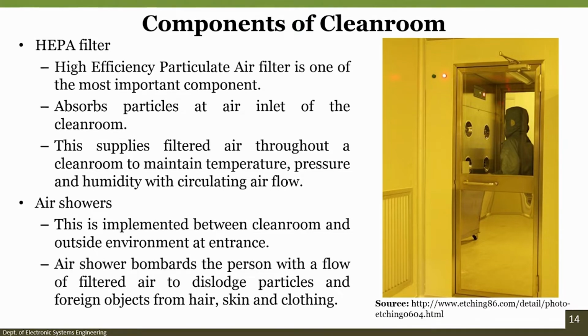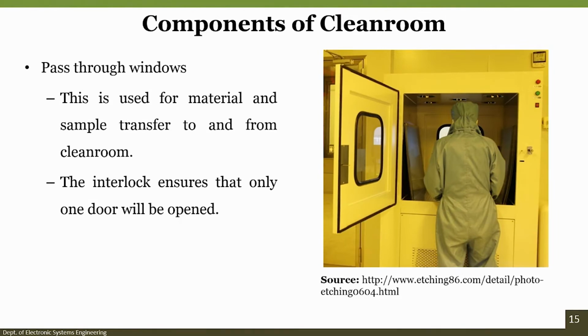Another thing that is very important in the clean room is the air shower. When you enter the clean room, the air shower will bombard the person with a flow of filtered air, and this bombardment will result in dislodging the particles. It can dislodge foreign objects, skin, clothing, and so on. Then I will send you a video of how the clean room looks, how to enter the clean room, what the protocols within the clean room are, and how the pass box works. For now, just understand that a pass box is used for passing material from one side of the clean room to the other side of the clean room.